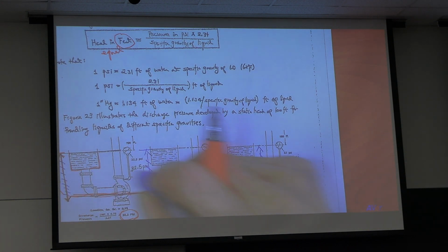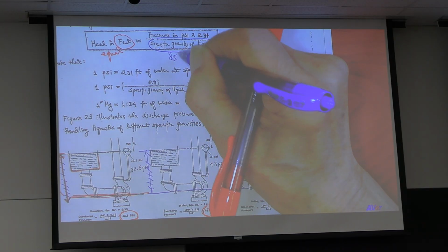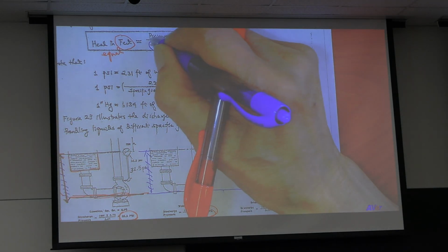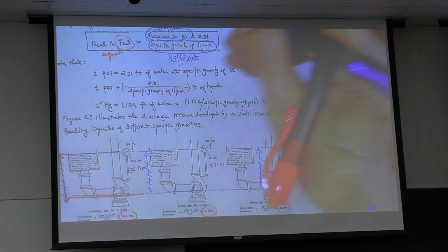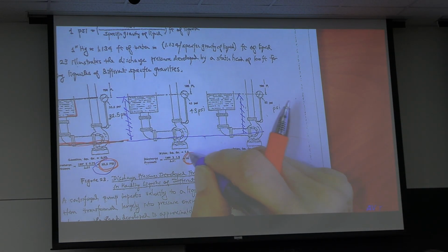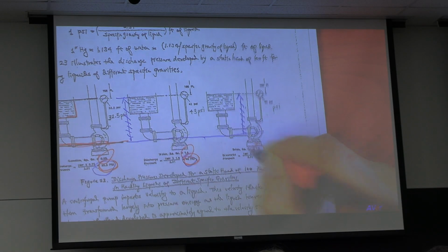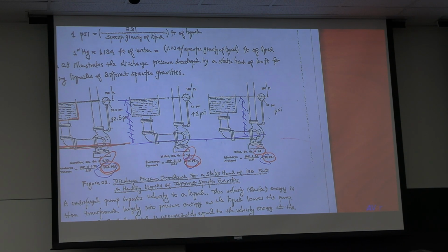But you're pumping 3 different liquids, specific gravity different. That's why the discharge pressure is different. Discharge pressure different, specific gravity different, but elevation remains the same. Okay, now keep going.